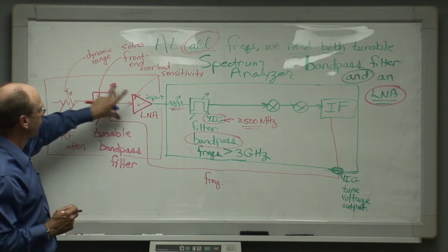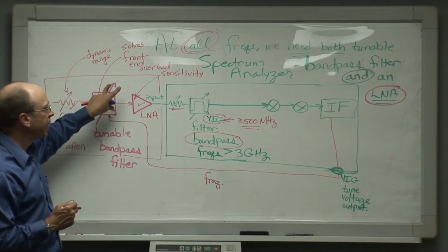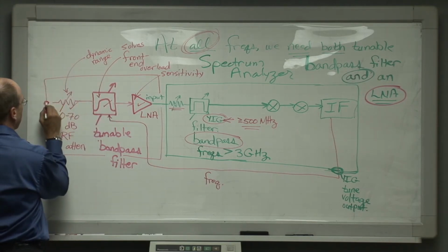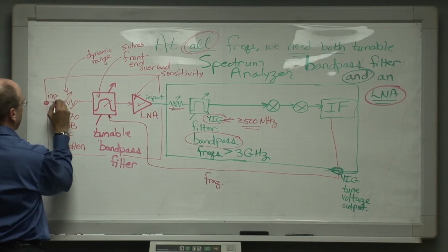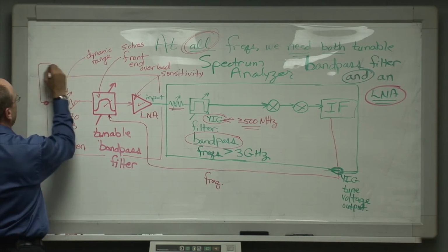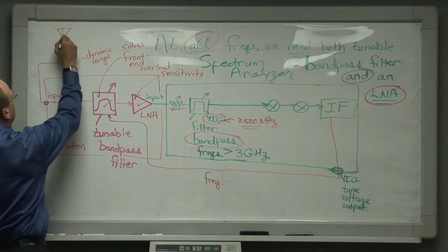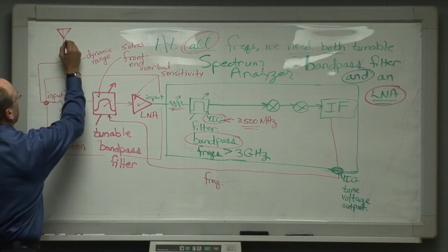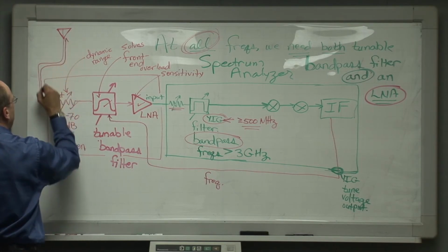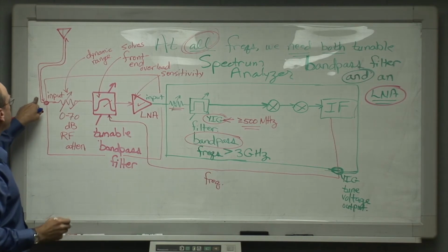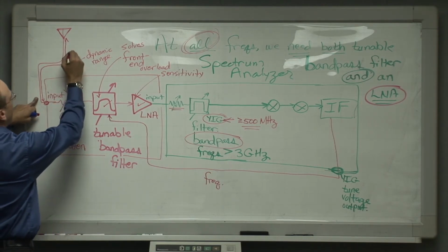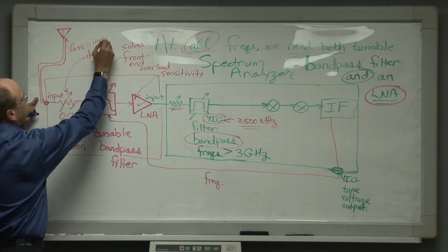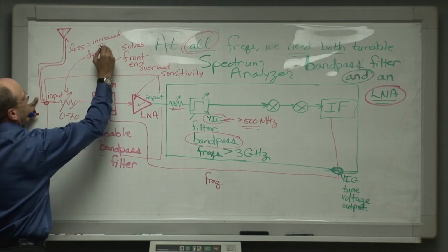To put it another way, if we don't put this front end up at our measurement antenna, then whatever line loss we have between the antenna and the input to this front end, so say we have this line going up like this, up to a measurement antenna up here, all of the loss in this line, which could be 30, 40, 50, 60 feet, just depends on our situation, is simply equal to an increased system noise figure.